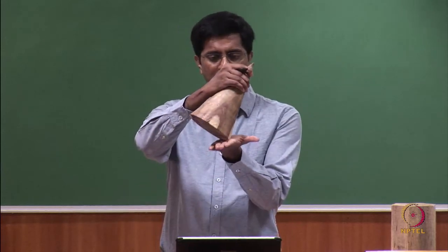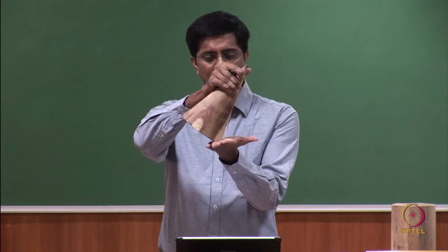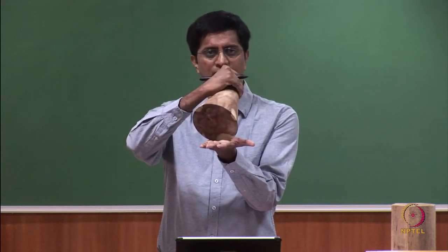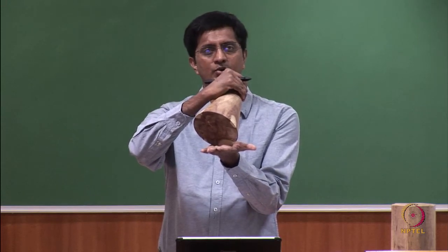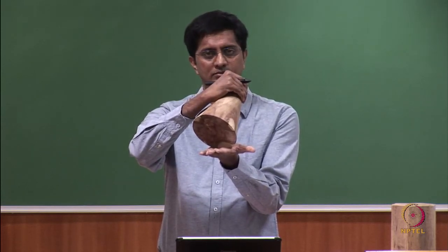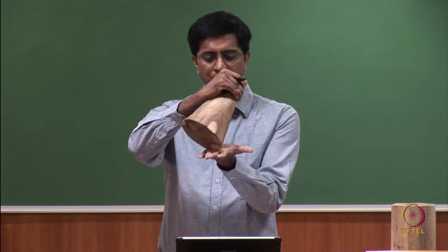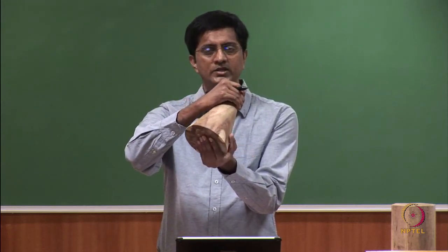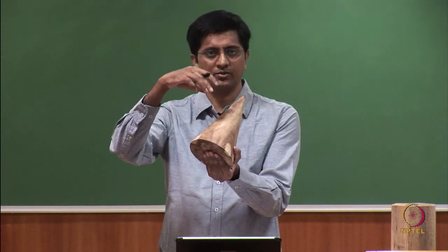Now, coming to the last view, where the axis is inclined to the vertical plane. Before rotation and after rotation, which shape will retain the same? Where will you have the true shape? Will it be in the front view or the top view? If you follow it clearly, you will notice that the top view will retain the same shape.